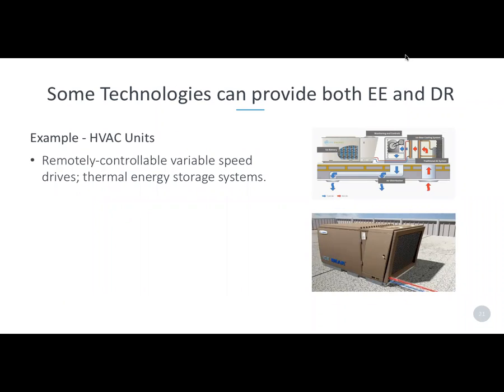I wanted to highlight a technology just as an example of a technology that works as both energy efficiency and demand response. This is one specific technology, but there's kind of an entire technology class of energy storage. This is a specific type of energy storage called thermal energy storage, and essentially it's an air conditioner that's full of ice or full of water, and you're able to use electricity to freeze the water at times when both the electricity is less expensive and when it's most efficient to do that. Typically at nighttime when temperatures are lowest, the compressors use less energy to create that ice.